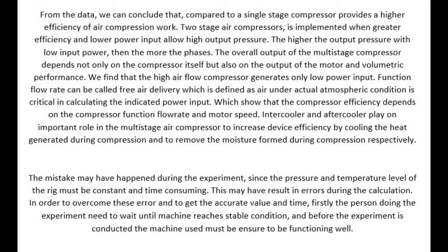Okay, now I will explain the conclusion for this experiment. From the data, we can conclude that compared to a single stage compressor, a two-stage compressor provides higher efficiency of air compression work. A two-stage air compressor is implemented when greater efficiency and lower power input allow high output pressure. The higher the output pressure with low input power, the better.